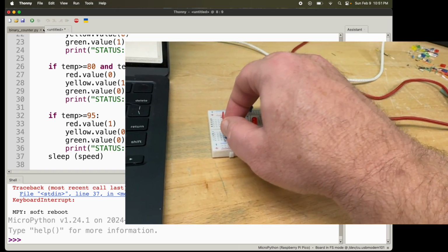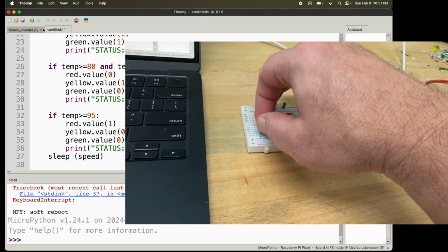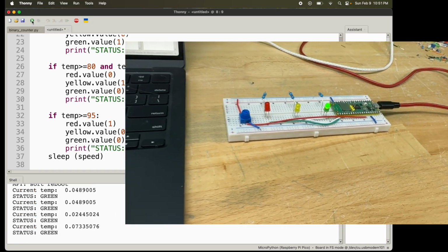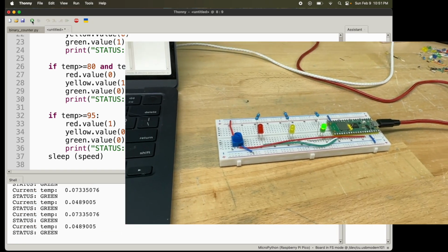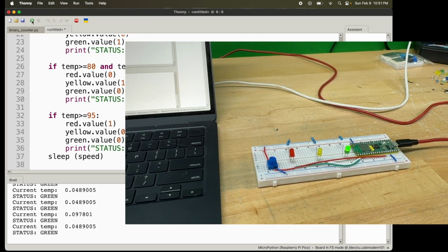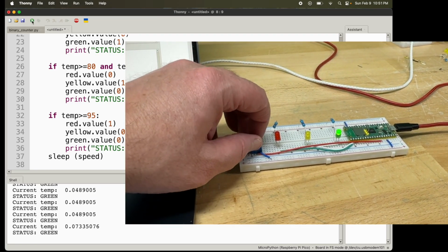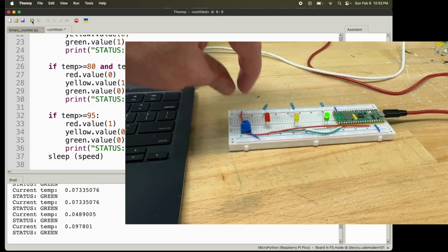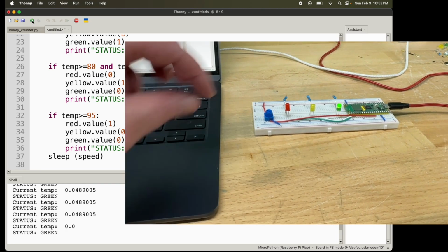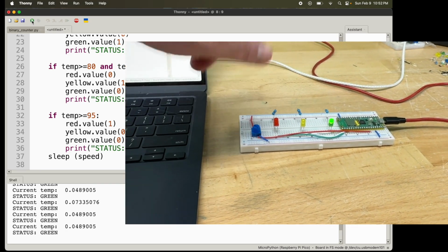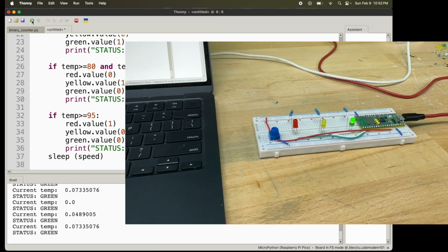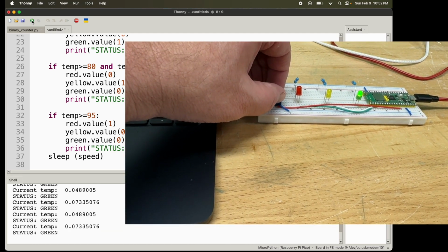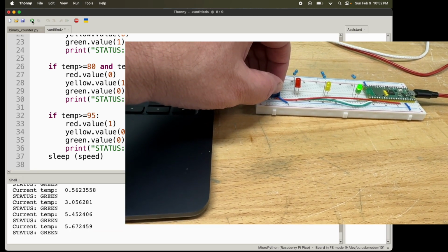I'm going to go ahead and, let's see, potentiometer is fully clockwise. I just hit go. Okay, so fully clockwise should map to 0, but in my case, it maps to 100. I could just flip this. The easiest fix would be to pull the potentiometer out and turn it around. I think that would probably do it. So anyway, as we turn, you'll see that temperature rise.